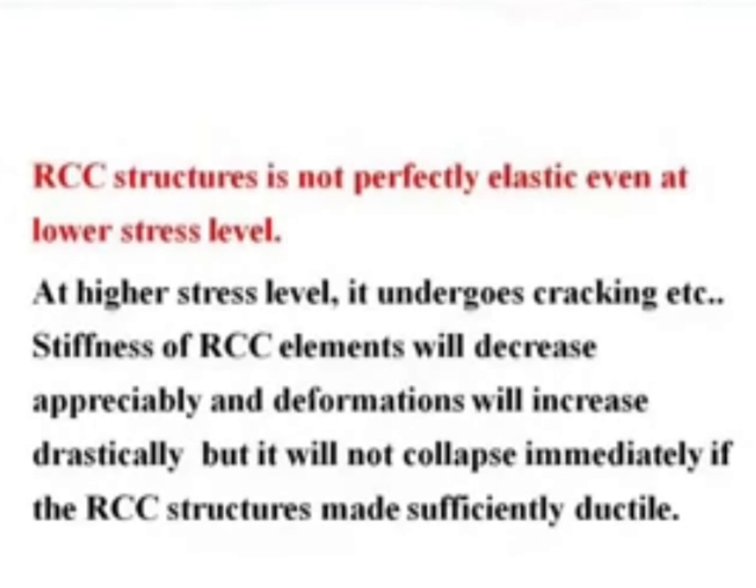In most situations, we consider the strain diagram linear. And we also just make an assumption that plane section before bending remains plane after bending, which leads to a linear strain diagram, which is also not correct in the case of concrete.